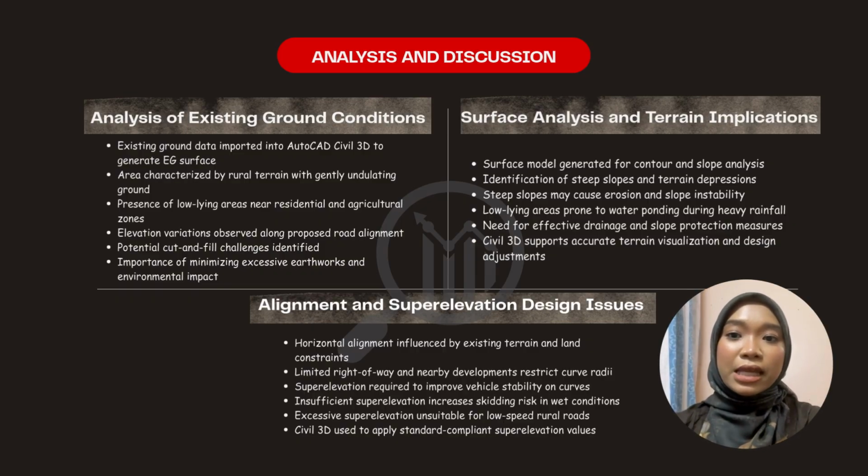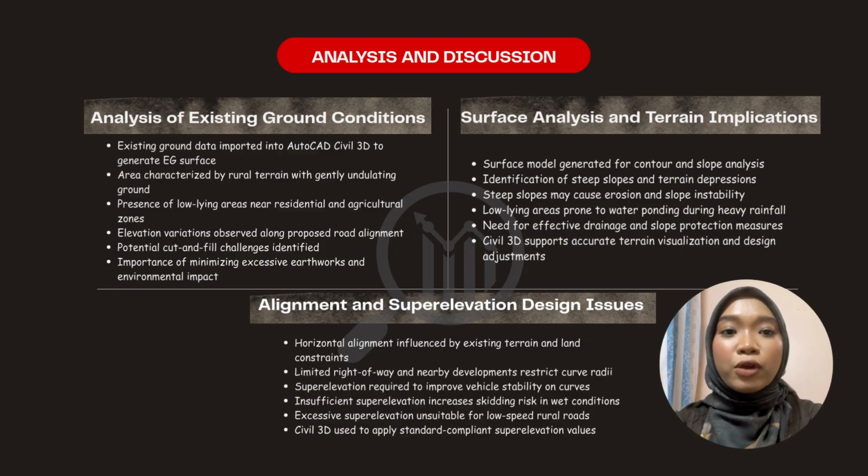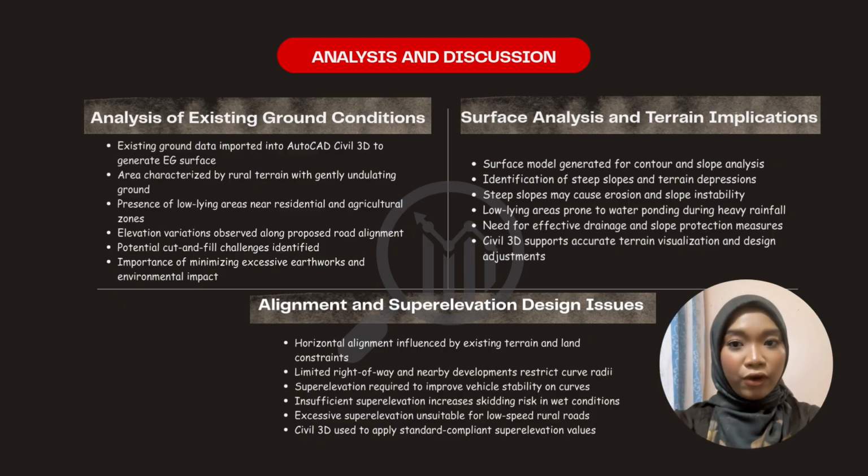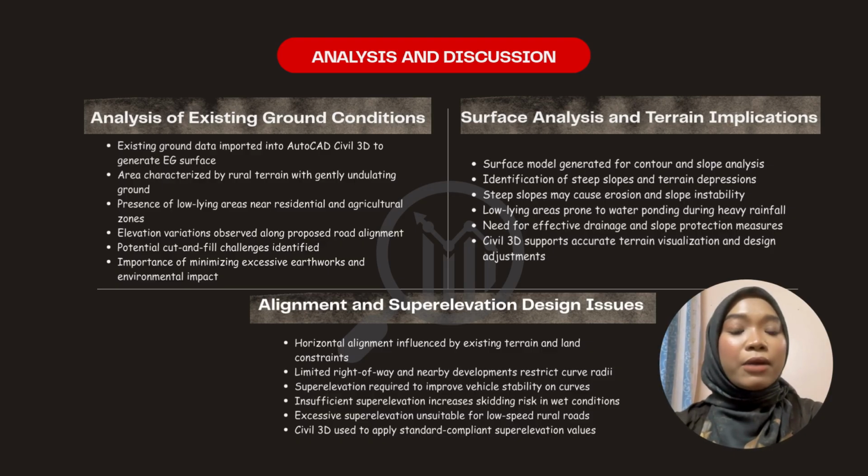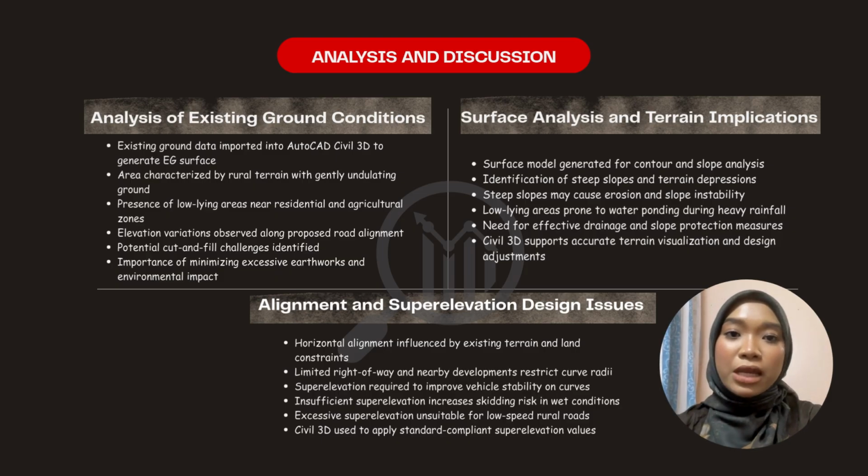Next, the surface analysis and terrain implication were carried out using Civil 3D tools such as contour and slope analysis. The result shows the presence of moderately steep slopes and terrain depressions. Steep slopes may increase the risk of erosion, while low-lying areas are prone to water ponding during heavy rainfall. These findings emphasize the need for effective drainage systems and suitable slope protection measures to ensure long-term road performance and